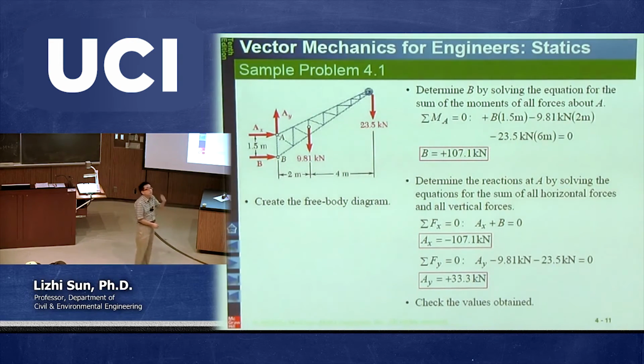And then we need to determine the direction, which means is it clockwise or counterclockwise. If you hold this point, this force has the potential to rotate this rigid body about this point clockwise. If it's clockwise, then you finally put a negative sign in front of the magnitude. So altogether, this is the moment due to this force at this point A. Any questions?